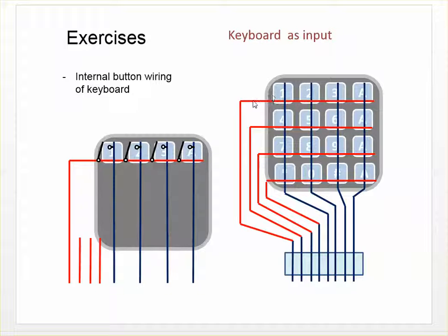After that, if no keys have been pressed, we can control from the P port so that this line will be 0, this line will be logical 1, and so on. In the same way we can go through this horizontal line and check whether any key is pressed. If not, then it goes to the next line and the next line.